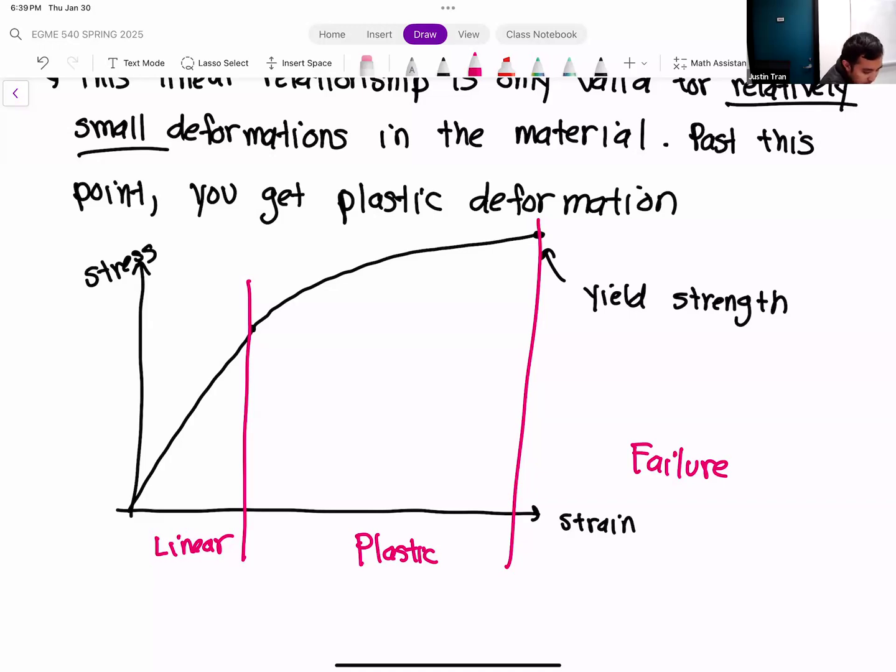Now, an interesting thing about ANSYS is that modeling or simulating plastic deformation is actually quite expensive. It's quite complicated because that's when nonlinearities creep into play. So ANSYS, at least the one that we're using, assumes linear deformation all the way through. In its default state, ANSYS doesn't have any way to know if your material is going to plastically deform or even fail.